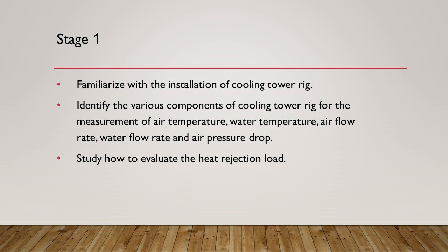In Stage 1, students should familiarize with the installation of cooling tower rig. Identify the various components of cooling tower rig for the measurement of air temperature, air flow rate, water flow rate and air pressure drop. And find out how the heat rejection load is simulated in this cooling tower rig.